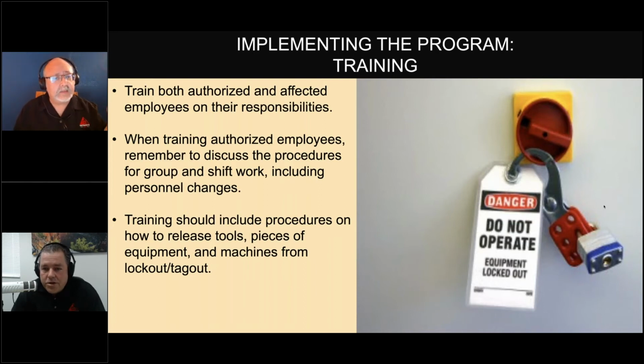Of their intent. Yes, when you're talking about that, authorized employees, and you'll find this in your lockout tagout protocol, whenever they're about to lock out a machine, they need to inform the affected employees. That will be part of the lockout tagout program. So they need to discuss the procedures of what they're going to be doing in that time period, or maybe multiple time periods. Maybe it's one shift and it's going to go over to a second shift. So they need to make sure that they discuss their plan with people within that system, right?